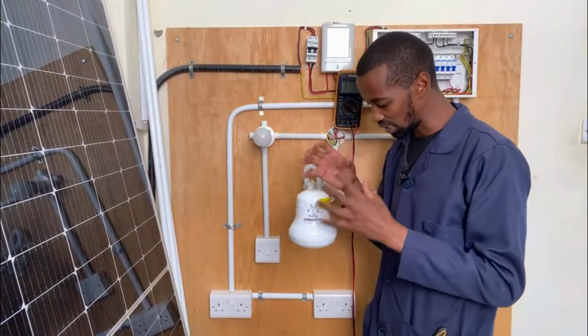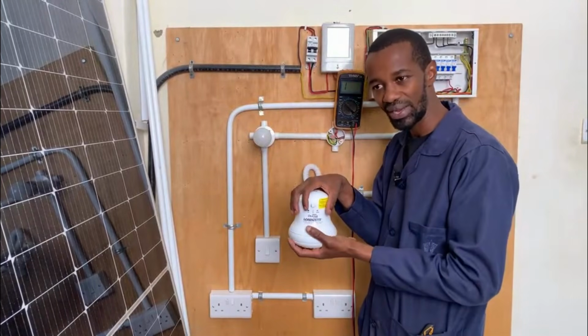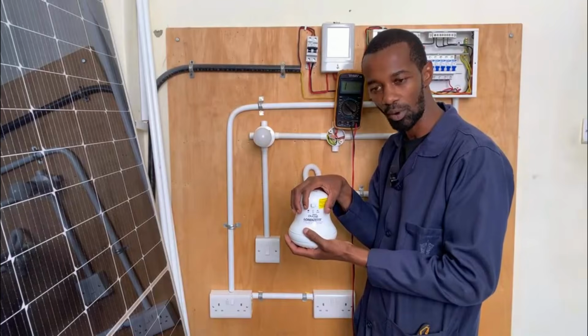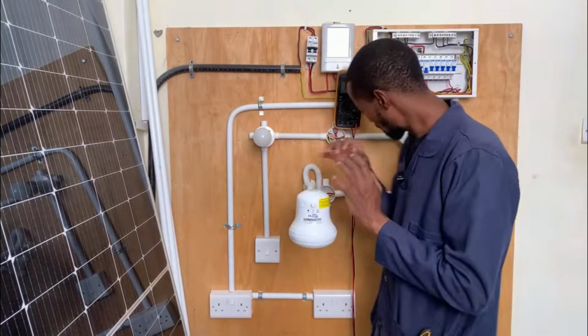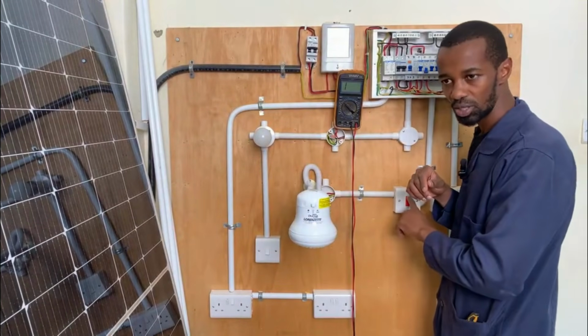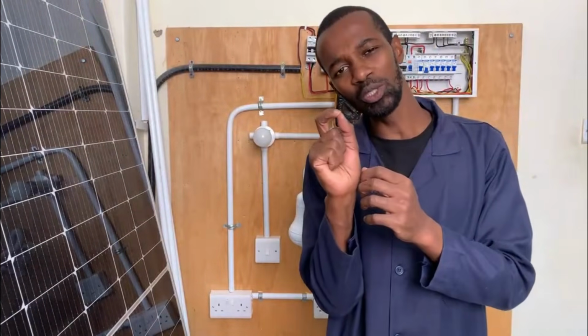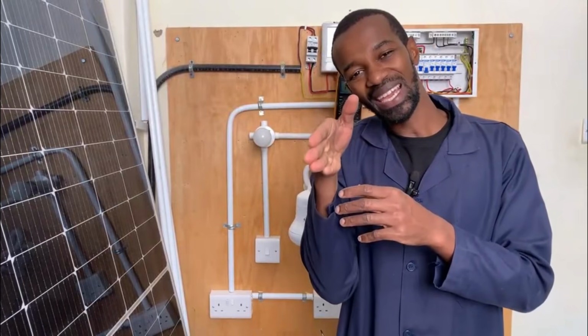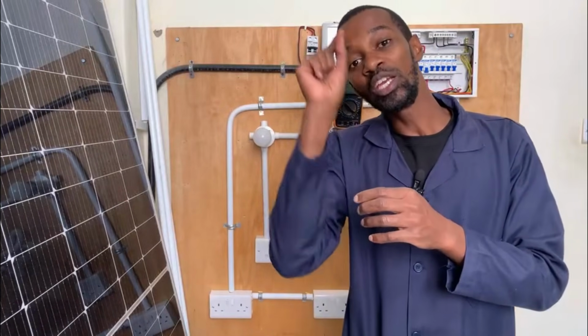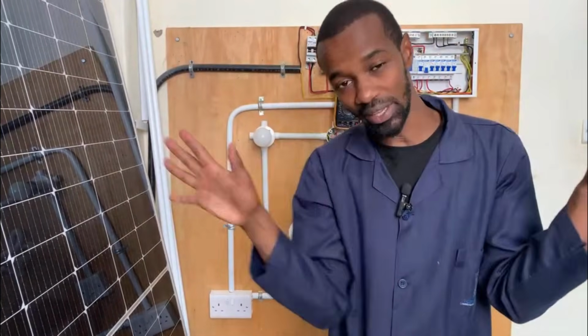If as an electrician you suspect this unit, the instant shower heater in that home, is the one that has a problem, zero down to it. Simply isolate at this particular point, switch it off, get to the consumer unit, where it is still off. Measure the output continuity between the line that is supplying that circuit and the neutral. That is usually the first suspect.